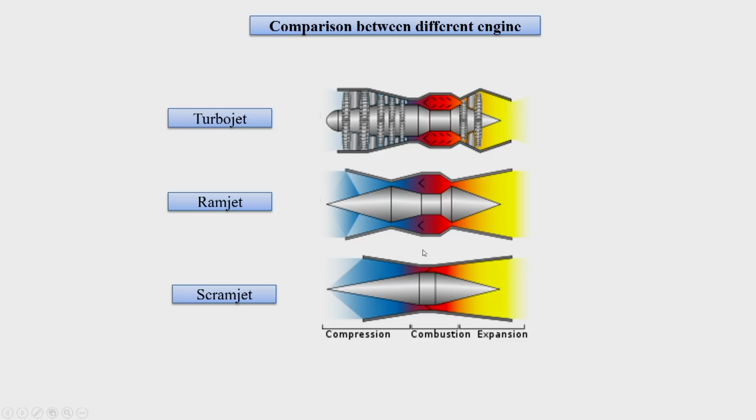So, in the combustion chamber of a scramjet we will have supersonic combustion. As the name suggests, scramjet: supersonic combustion ramjet engine. After combustion the gas will expand. The major difference after the process of combustion is in the nozzle. In the case of a ramjet engine, the nozzle has to be a convergent-divergent section such that the entry to the nozzle is subsonic.